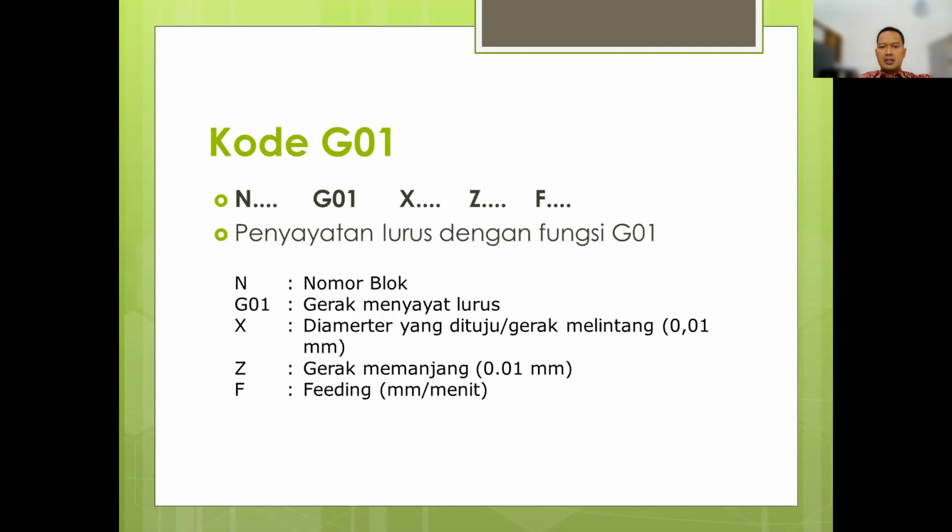And then G01, you can write in the format of N, G01, X, Z, and F. This is for linear machining with the feeding.